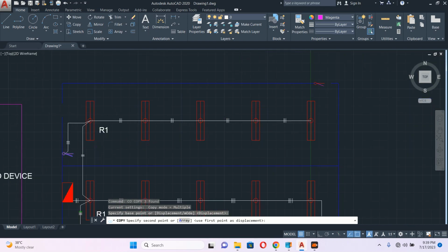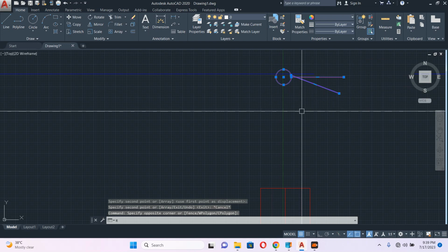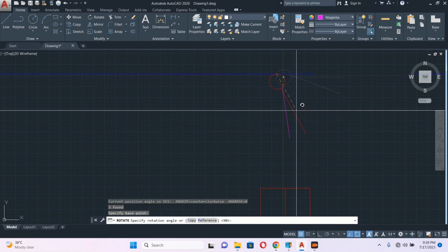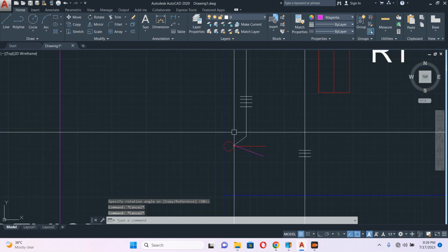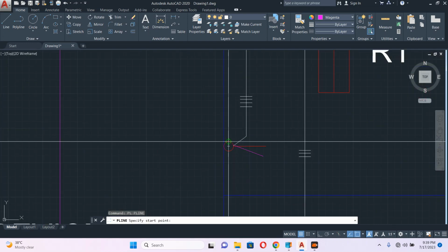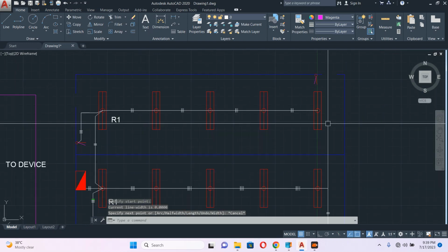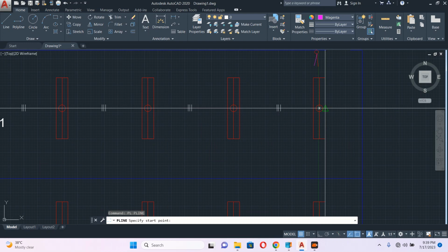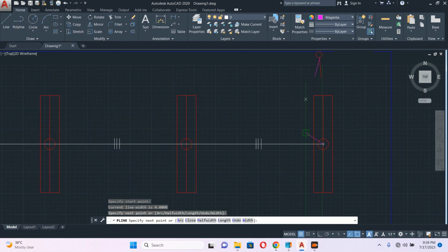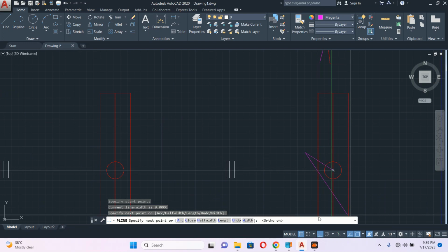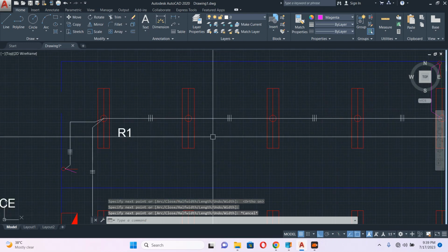Sorry, not intermediate, a two-way switch actually, not intermediate, sorry. Rotate. Then there will be another conduit. You can use the same line, so there is no need to put an extra conduit. But some sites use an extra conduit to save the wire. Here no problem because it's the same.